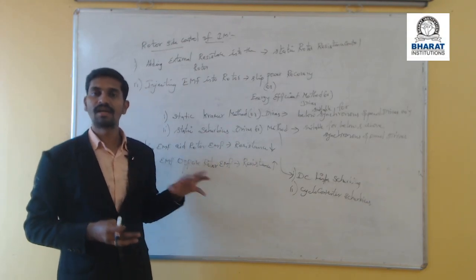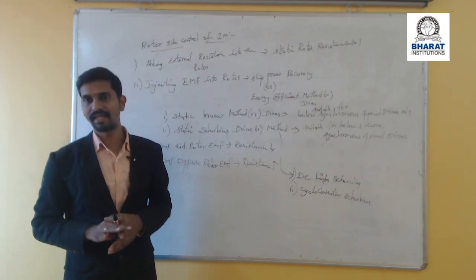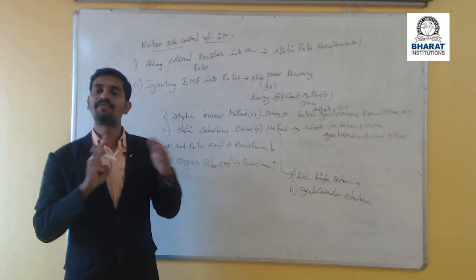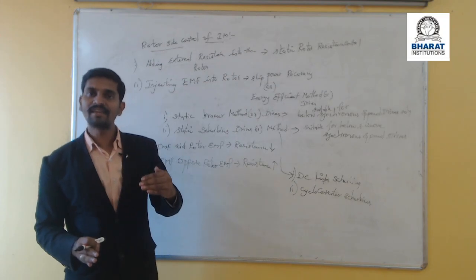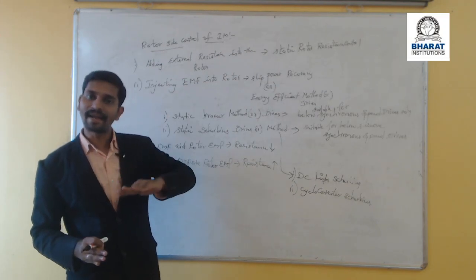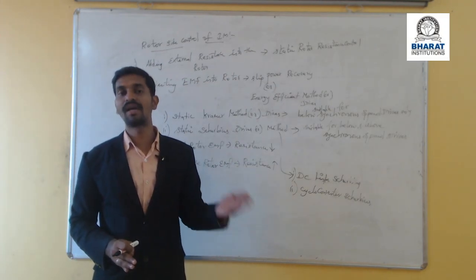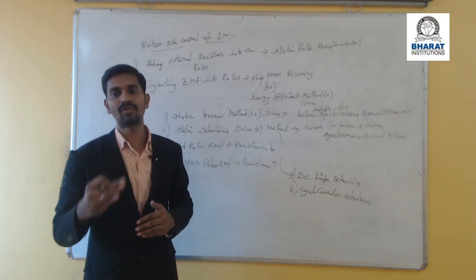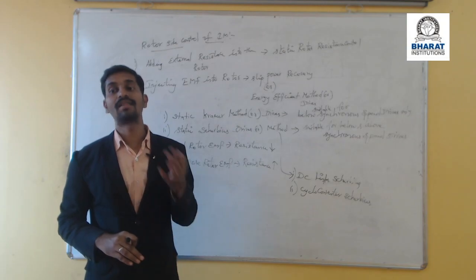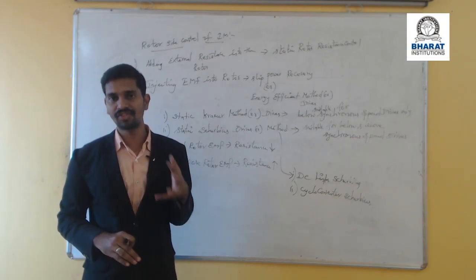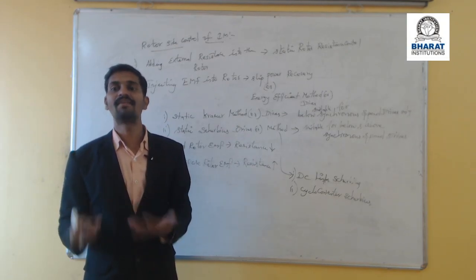With this, today's session is complete. Today we discussed the rotor side control methodology. The rotor side can be controlled by adding external resistance into the rotor circuit as well as by injecting EMF into the rotor circuit. If you add resistance into the rotor circuit, the disadvantage is that power will be wasted.